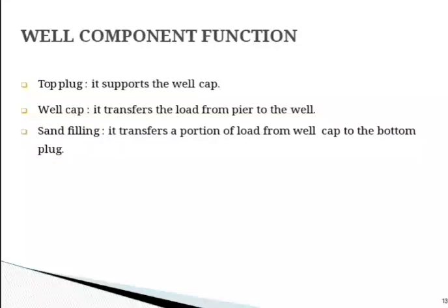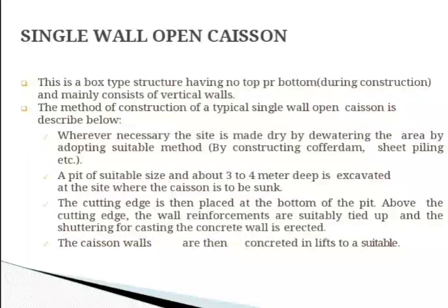Next, well component function. The function of top plug is to support the well cap. It transfers the load from the pier to the well. Sand filling transfers a portion of load from the well cap to the bottom plug. Next, single wall open caisson. This is a box type structure having no top or bottom during construction and mainly consists of vertical walls.